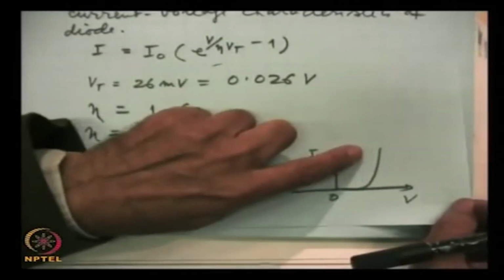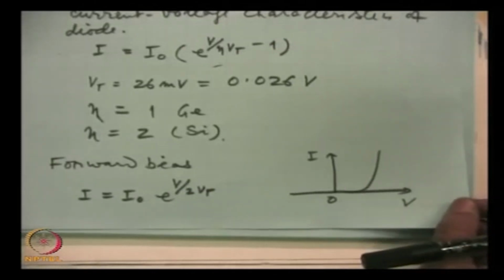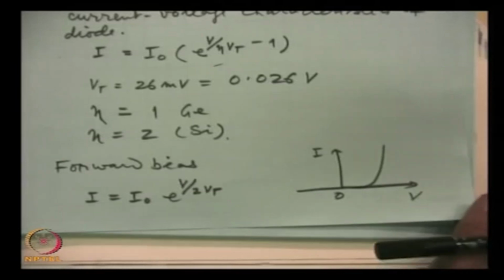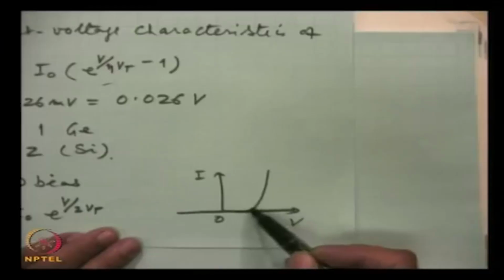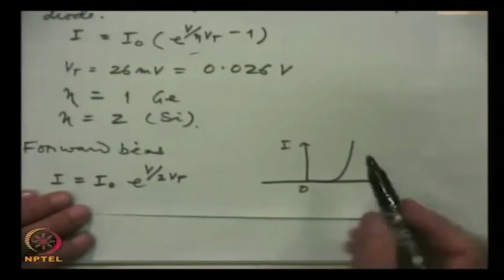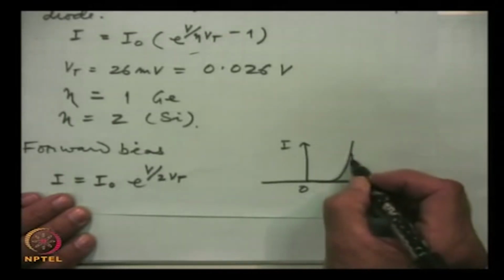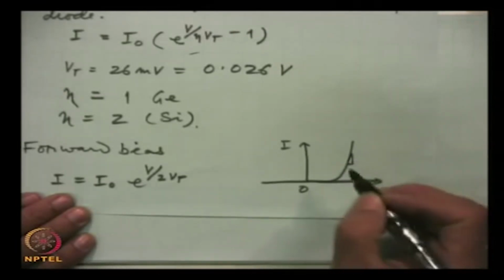The current should not exceed the prescribed rated current for the diode by the manufacturer, so to limit the current we normally use a resistance in series with the diode. It is understood that current increases exponentially with forward bias, and another thing is that we can find the resistance of the diode in the forward direction by taking this small triangle.